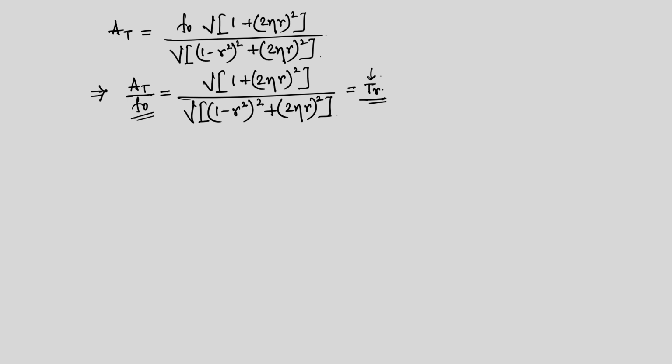So, if you design the foundation, then obviously you have to find out this force before you start your design. And that gives us the complete idea of when a structure vibrates under support motion, or if we have a sinusoidal force, how much force is transmitted to the foundation.